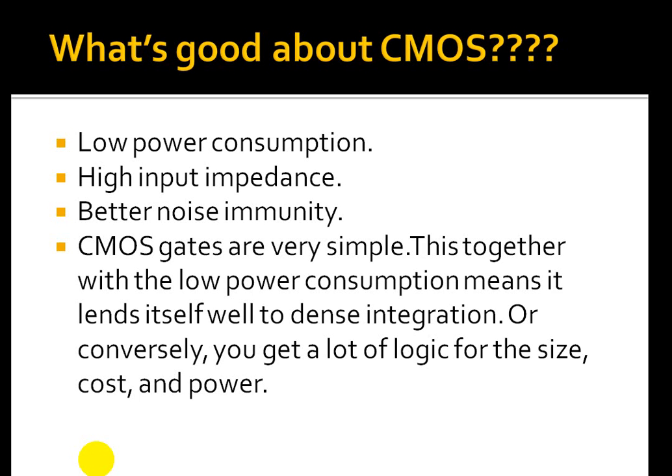So in noisy environments, a higher VDD is preferred, so we get better noise immunity. So we can say that CMOS gates are very simple, and together with the low power consumption, it makes for dense integration. That is, we can incorporate more transistors in the same size of IC. So we get very good value for the cost, power and size. This is the reason why CMOS logic design is very useful in VLSI system designs.